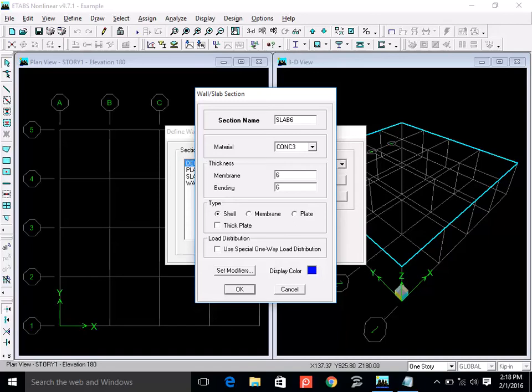Because you have a mesh of steel bars, longitudinal bars. Those steel bars help concrete in resisting bending moment. So the slabs resist bending moment. It also resists shear force, right? So in theory and in practice, or in real life, I should say, the slab should be modeled as shell.